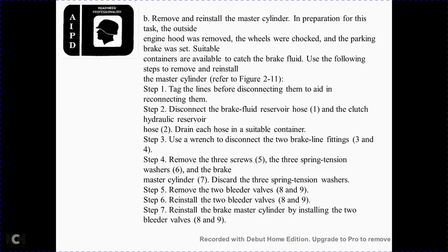Step 4, remove the 3 screws 7 and the 3 spring tension washers of the brake master cylinder, and discard the 3 spring tension washers. Step 5, remove the 2 bleeder valves 8 and 9. Step 6, reinstall the 2 bleeder valves 8 and 9. Step 7, reinstall the brake cylinder and install the 2 bleeder valves 8 and 9.